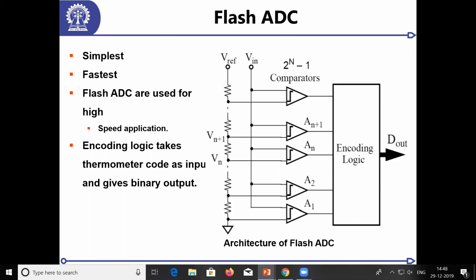In RF design, inductor comes in. And of course, a transistor is there, which is a controlled current source. So there is a resistor, and these voltages are generated using it. So this is 0.5 volts, and the rest of the other voltages are there. These go as an input to the comparator, and the other input is the input signal. Now, it's a flash ADC, so it should quantize in a flash. So the clock comes in, triggers the comparator: tell me whether it is greater than or less than the threshold. Suppose the signal is over here. How many comparators are there? C0, C1, C2, C3, C4.